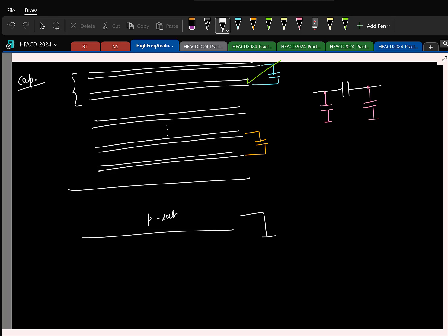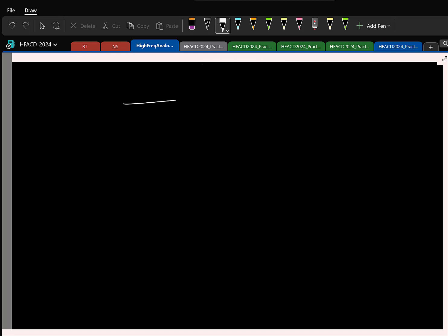And this basically, if you actually see, the spacing will actually keep increasing as you go to higher metal layers. That is not under your control. Typically, you will find that the distance from the topmost metal layer to the layer below will be quite large, so that you don't have these parasitics so much. So yeah, now the capacitance is straightforward. You just have two metal plates. Let me take you to something. You have two metal plates like this.